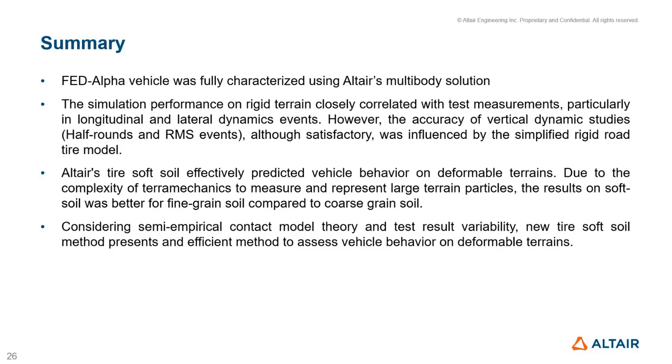But we saw, however, that for the vertical dynamic studies, for, let's say, the half round and the RMS events, although good, the results were a bit influenced by the simplified tire model. And that's known to us. It's known because we didn't want to use a 3D part tire solution to capture the vertical dynamics, which is needed in this analysis, such as CDTire or FTire or MF-Swift, as the main goal of the project was to validate the soft soil. So we kept with the MF tire that we have, which is free of charge. And the intention of this work is also to share with people, and we don't want them to need an extra license to run the model.